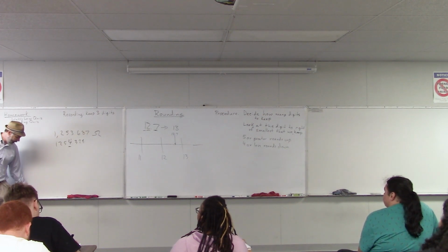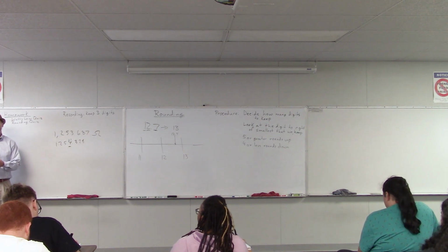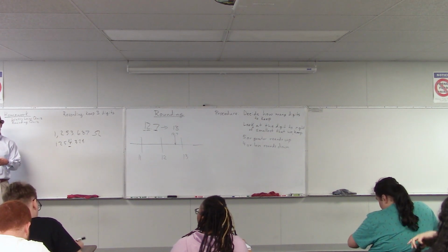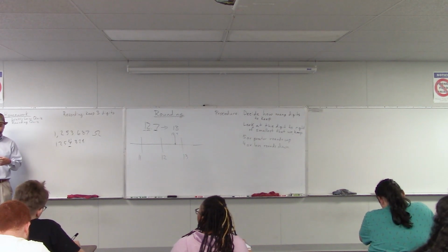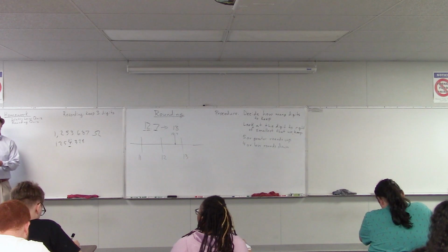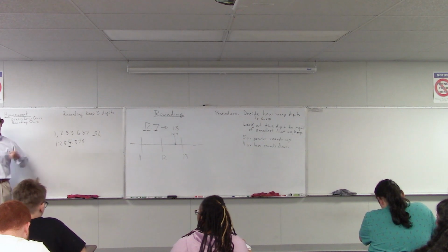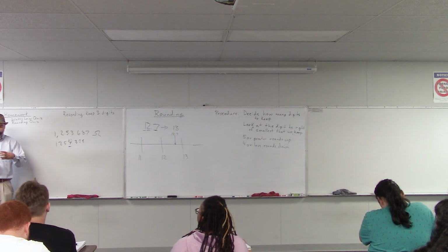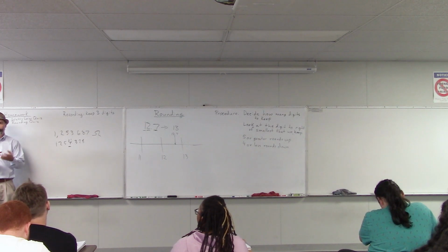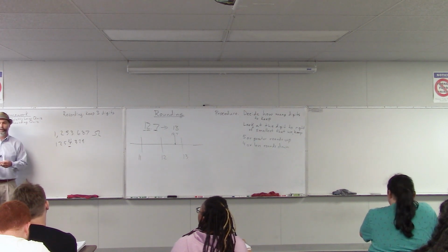In other cases, it's much higher. Sometimes you have an instrument that needs to be very precisely controlled, but it's out in the field, and they know that it would be hard to get the temperature down to 72 degrees if something's out in the sun. So sometimes they have little ovens built into these where they heat it up to say 200 degrees. But they know that it's always 200 degrees, and that way that reduces the resistance fluctuation based on temperature. So there can be specific temperatures, but they vary from application to application.